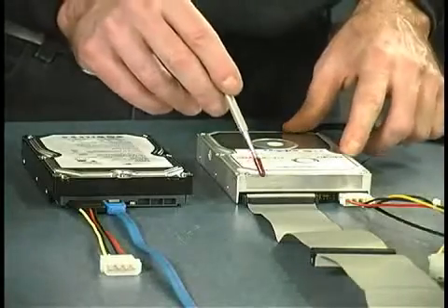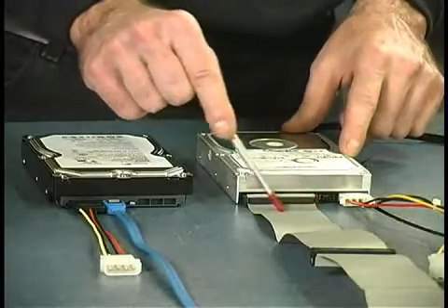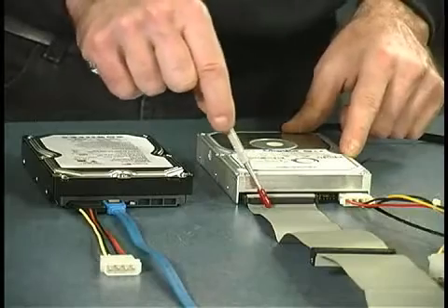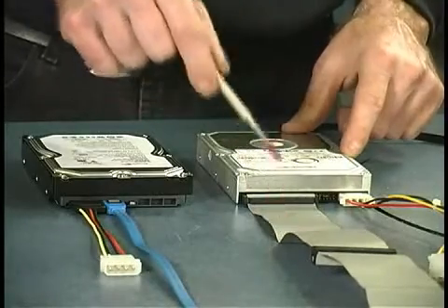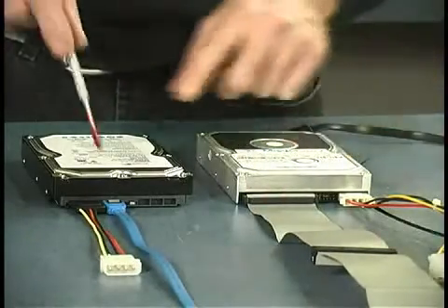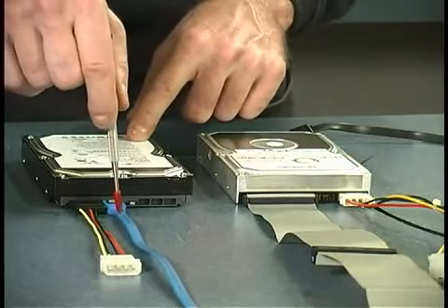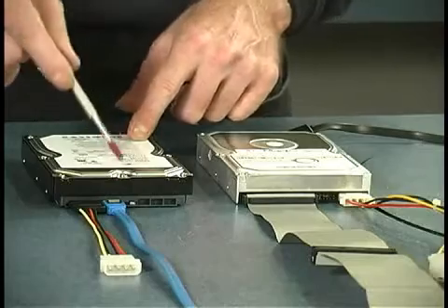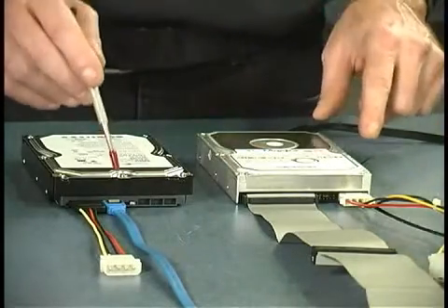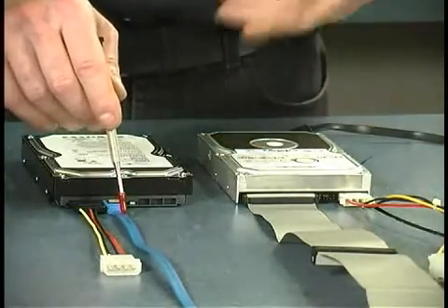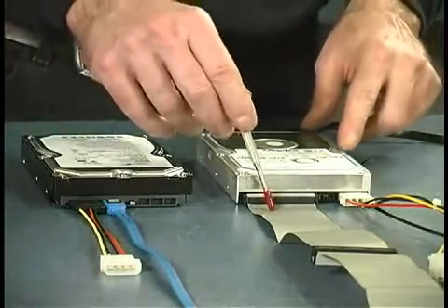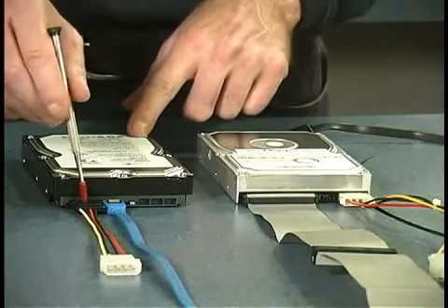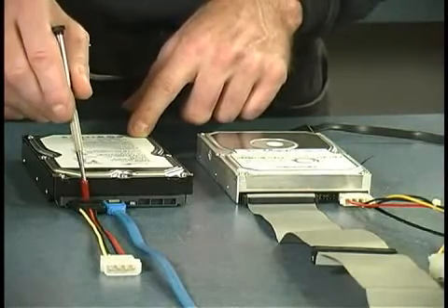As you can see with the older parallel drive, the reason it was parallel is because it had a multi-pin connection. It had 16 bits actually of data going down this cable simultaneously, and that was a parallel transfer. On the newer serial ATA, we have only a 7-pin cable, and literally only 1 bit at a time is sent down the wire. So obviously with the serial ATA, you can see that the cable is much smaller and easier to handle. It's not this wide ribbon cable. But also there's a couple of other differences. One is the power connector is different. Serial ATA drives generally use a different power connector.